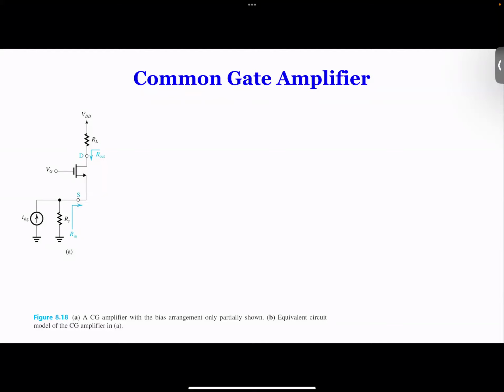So you have to have this resistance or something else. This one, without an AC signal, because this is current, right? When you don't have a current, it's open circuit. So we have to have something here. And then on the top, we have RL, which is the load resistance. The reason we have that is because we need to connect it to VDD. And of course, in the future, we can replace that with a current source as well. But for the time being, we use RL for the simplicity of analysis.